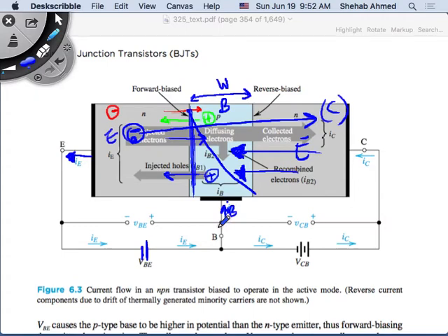So remember, versus the MOSFET, the MOSFET was controlled by VGS, the gate to source voltage, right? As soon as I put in gate to source voltage, I've charged my plates, meaning I've created my channel. I've created enough overdrive voltage to create the channel width, and that's not drawing current anymore.